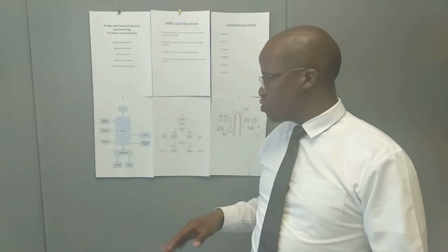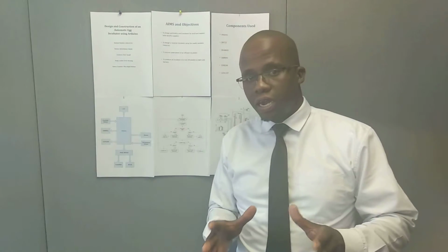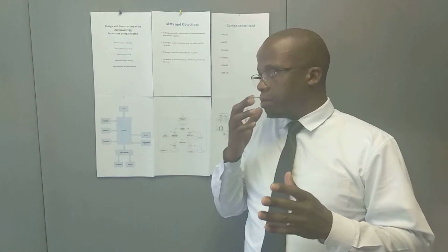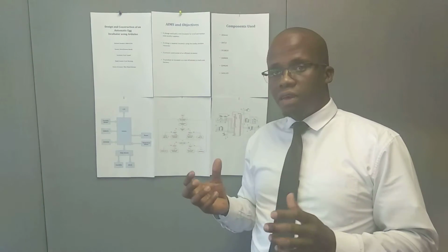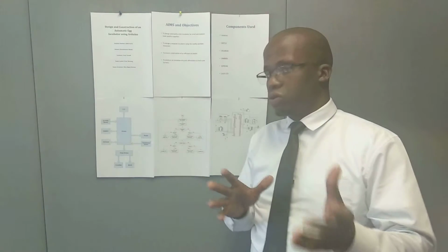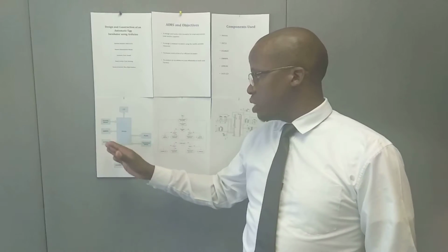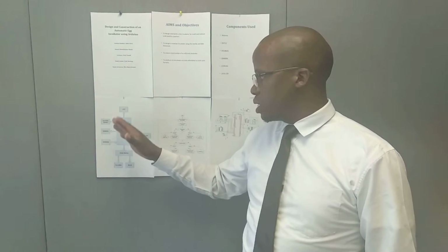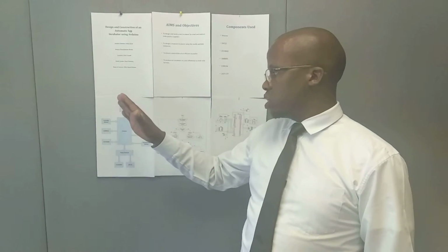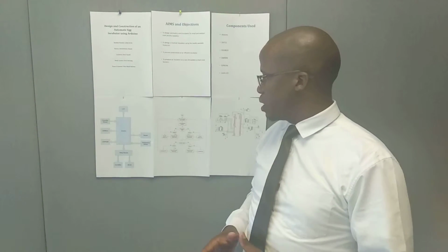We have the relay module that is connected to the humidifier, and also the bulb. In this case, for heating, we use the bulb, as it's more effective in this scale. It provides enough heat to actually run the whole incubator to the required temperatures. We have the ESP8266 and also SIM800 and the humidity sensor.